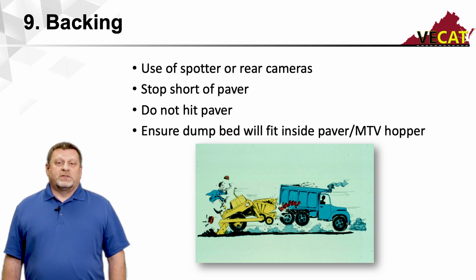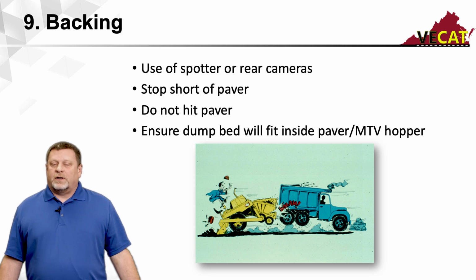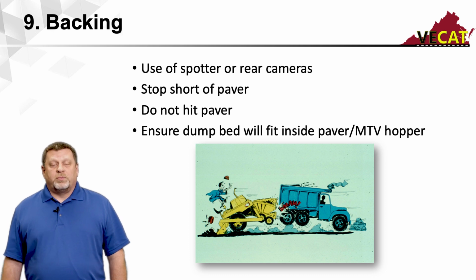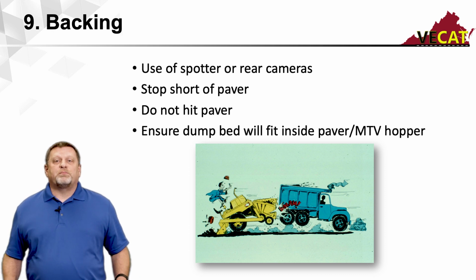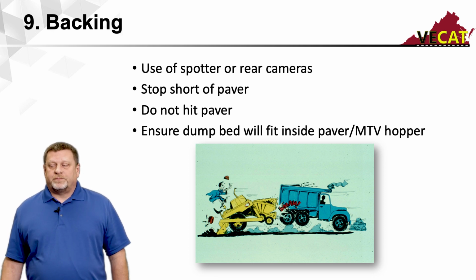But it's important, as we stated, that the trucks stop a couple of feet prior to initiating any kind of contact with the paver. Once he's come to a complete stop, the driver needs to put it in neutral and hold a little pressure on the brakes, just a little, and allow the paver to initiate contact and begin to push that truck forward, versus trying to make a complete contact with the paver.